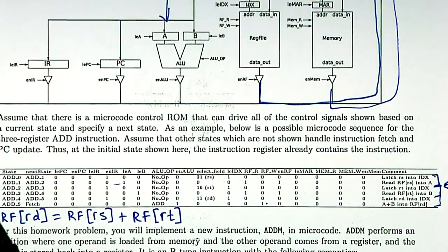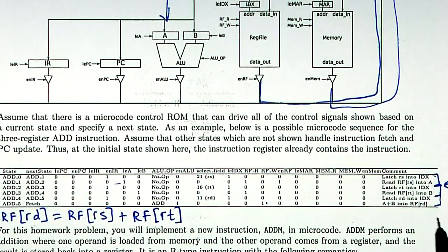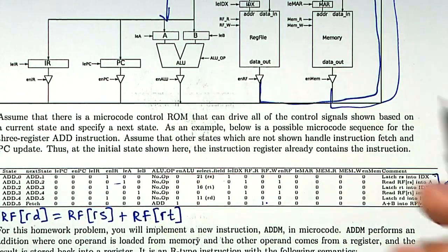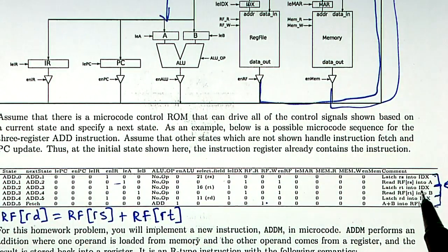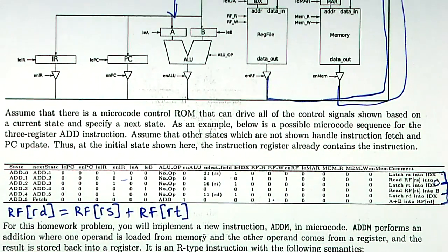So it would come down to adding this extra line of microcode where we supply all the data signals in order to perform this operation. And then we modify this previous state to not write into A, but rather the memory address register. So I guess we can continue after the break. Go ahead and take a break until, what, like 15 past? I think 15 past would be good.